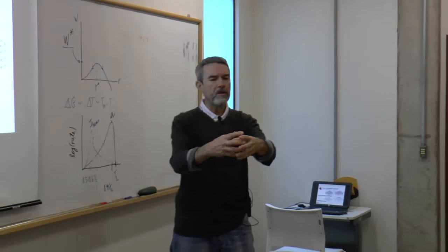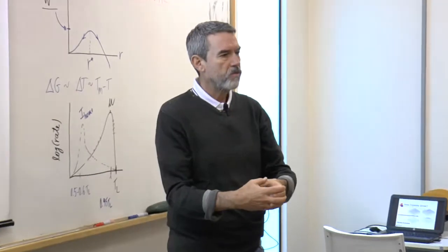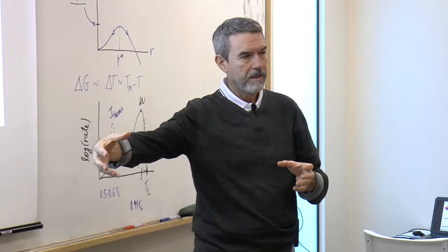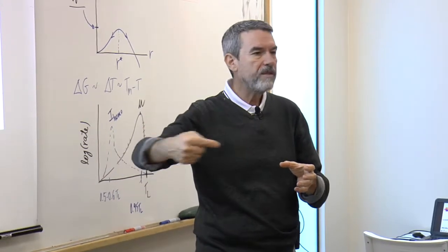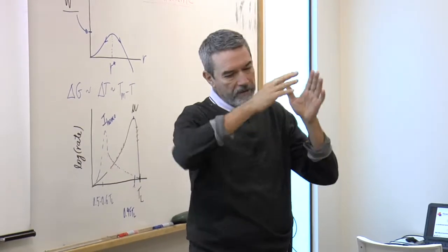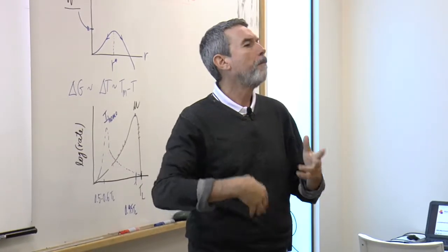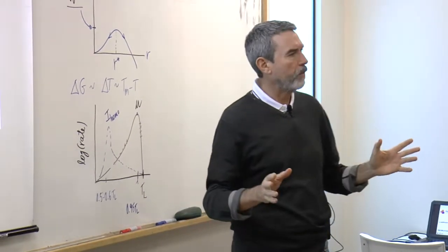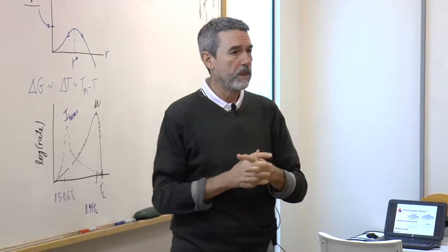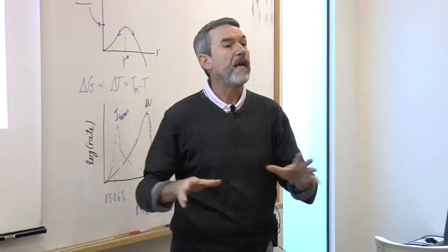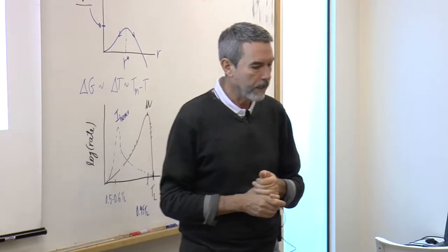When the composition of the crystal phase is widely different from the composition of the glass, then long-range diffusion has to occur, and then you have depleted layers, you have more complicated situations which can be dealt with, but I'm not going to tackle those problems today in this class. Okay?